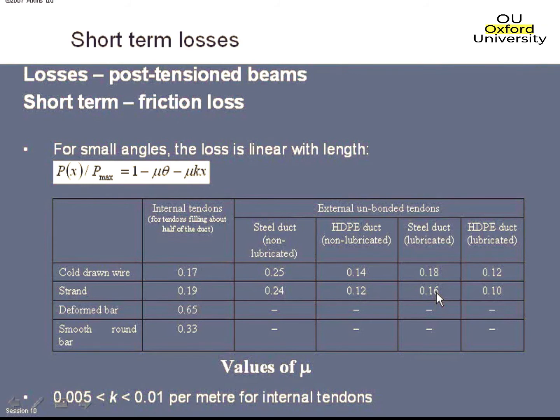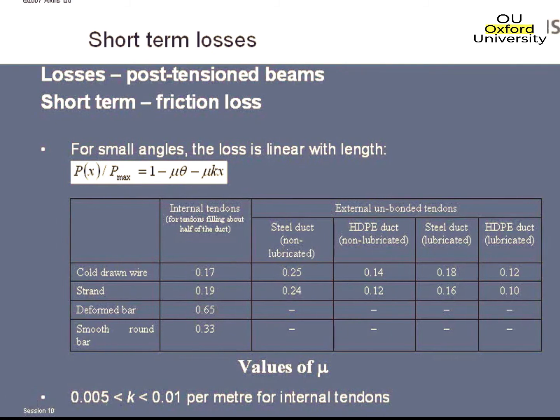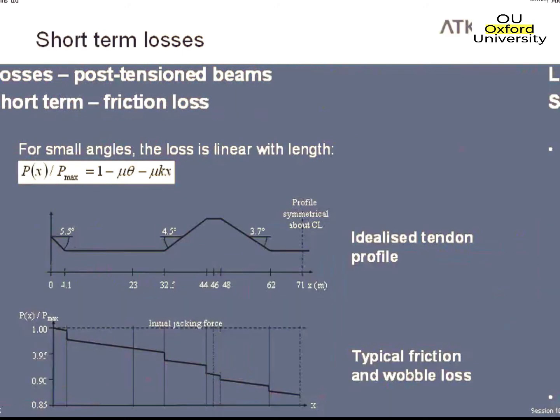I would suggest that we don't use those. I would suggest that we do what we've been doing in the past when we've done post-tension design: have in mind somebody's system, whether that be VSL or Freyssinet or whatever, and then just use those values for that particular system and quote those as what the design's been based on. There's nothing new. This is only what we would have had to do in BS 5400.